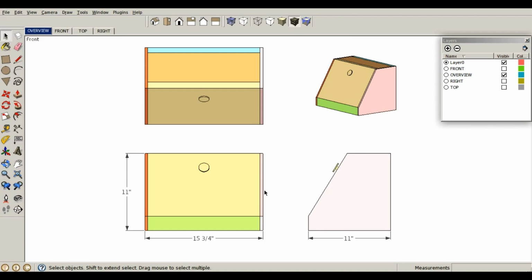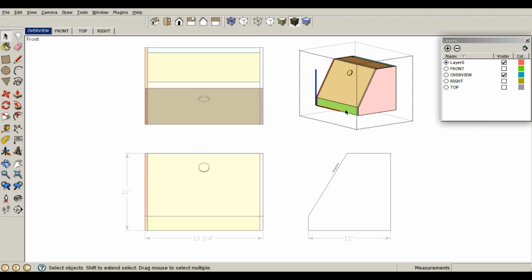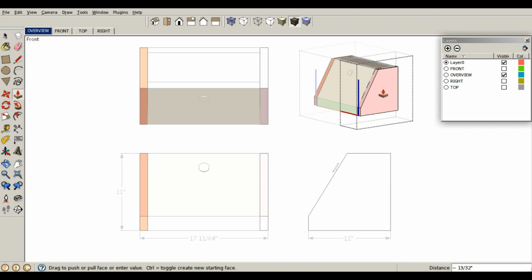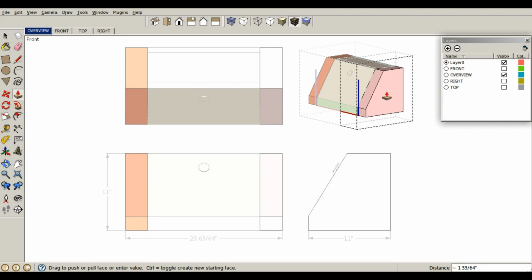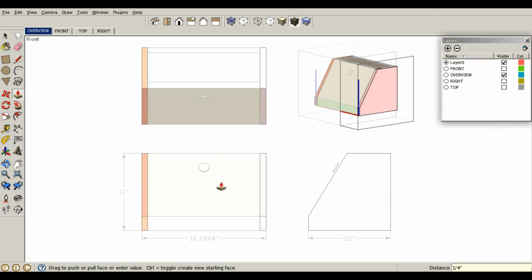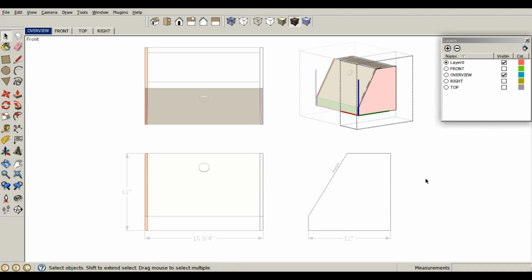So let's just say for whatever reason this needs to be a 1/2 inch wider overall, so I need to add a 1/4 inch of width to my side pieces. Okay, so if I double click here, now I'm editing the project. Well, I want to edit the part in the project. P for push pull, and let's pull this, and as you can see on the bottom there, it's kind of grayed out, but all my dimensions are being updated in real time. So if I just pull this direction 0.25 to one side, they are copies to begin with, so it updates both sides. And just that easy, you can manipulate the entire two-dimensional drawing. So let me Control Z to back up. And I hope that makes sense.